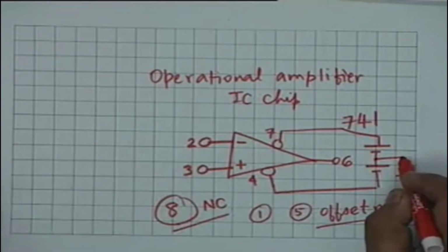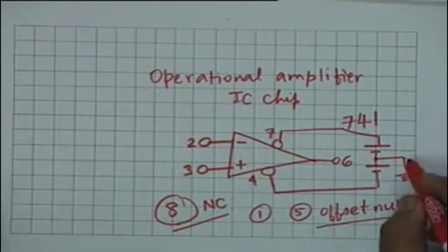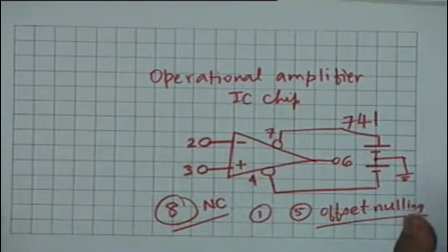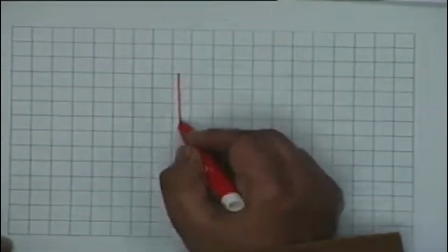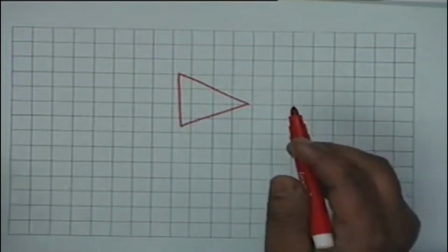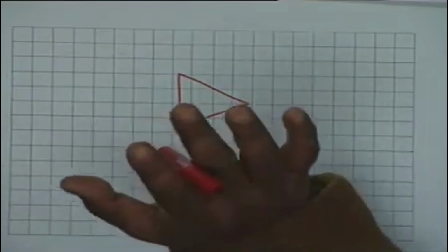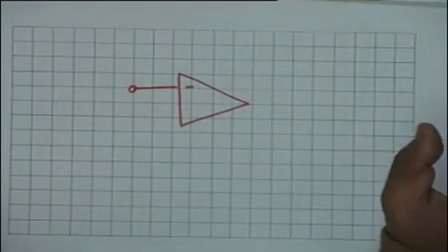This is obviously external. The 741 chip provides no ground. The ground has to be provided externally by means of the power supply. So the reference is set outside the chip. All right. So this is 741, and if I represent this now in a simple form, all that we are concerned with is the input and the output, because we refuse to look at what goes inside. So the terminal connections are, we also forget about the pin number and all that.